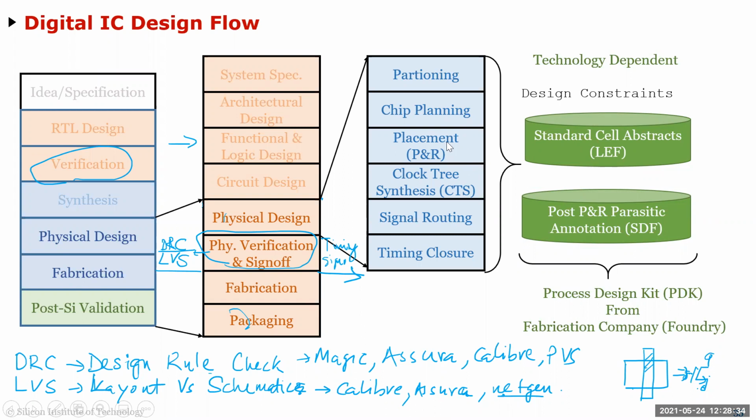When the tool is trying to do place and route, if it used the real layout, it'll take forever because the data is so heavy. It has every micrometer of data, right? The contacts and all that. But when Santanu teaches you the standard cells, he'll show you that the standard cells are done with very rigorous regularity. So the LEF captures this regularity. It just tells you, okay, the cell is 10 micron by 40 micron. The via is sitting at 1 by 1. And the place you can route is this region from 10 micron to 20 micron.